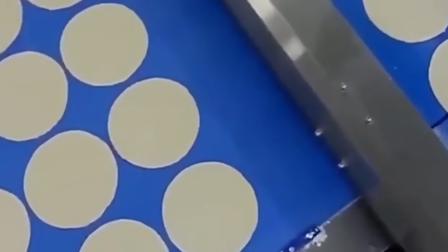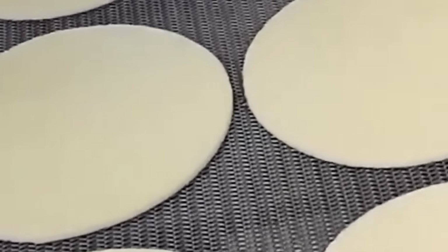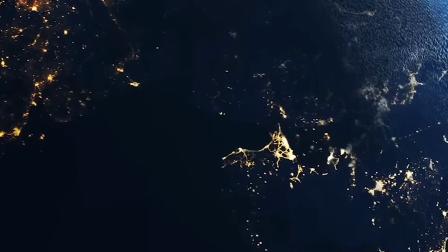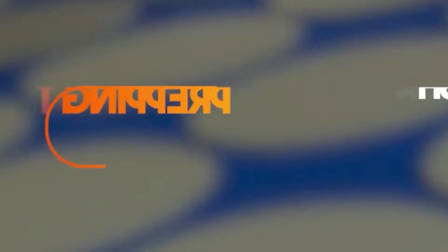Pressed dough discs are transferred to perforated baking pans or screens using a vacuum lifter. A light mist of oil is applied to the pan surface to prevent sticking. The dough and pan then move along a conveyor to the topping line.